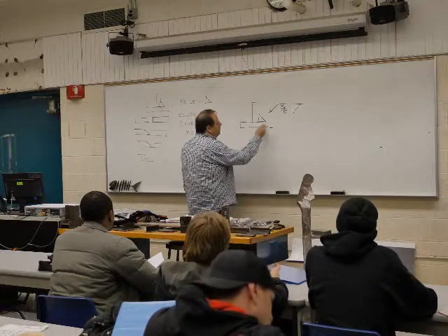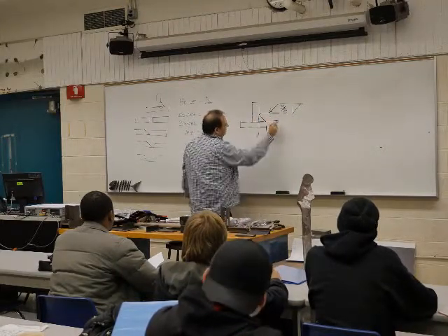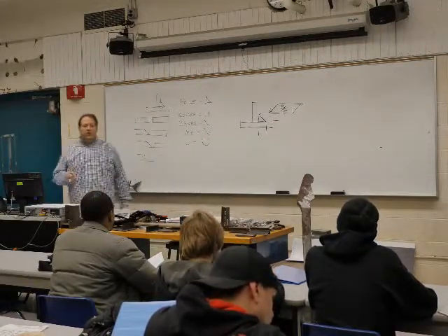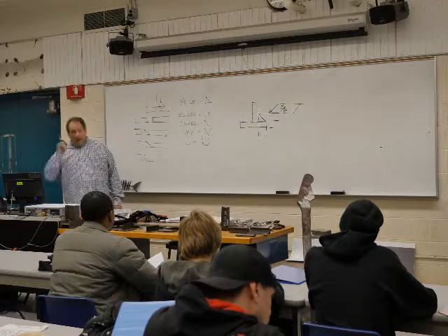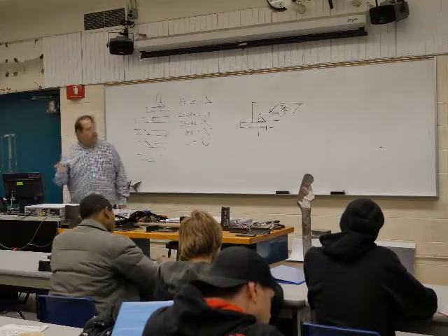This is a leg of the weld, and this is a leg of the weld. Right there. Those have to be 3/8. Both those have to be 3/8 to make it a 3/8 weld.